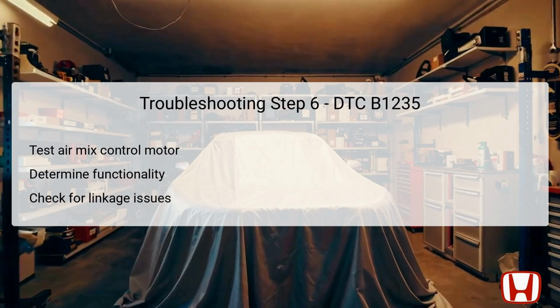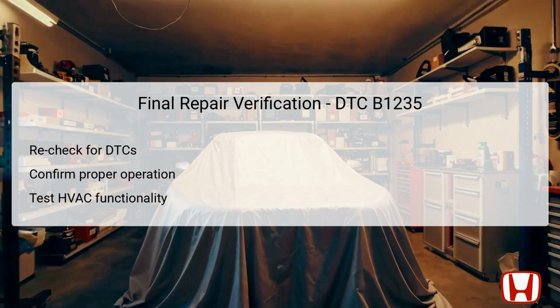Conversely, if the air mix control motor tests negative, then you can proceed with either replacing the motor itself or repairing any issues with the linkage or the door that connects the motor to the air mix control system. A thorough examination of all components is paramount to ensure that the root cause of the problem is effectively identified and resolved.